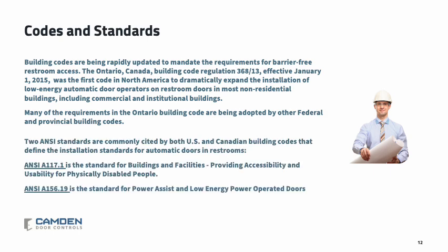There are two ANSI standards that are commonly cited in regards to the installation of automatic doors in restrooms. ANSI A117.1 is the standard for providing accessibility for physically disabled people, and ANSI A156.19 is the standard for low energy power operated doors.